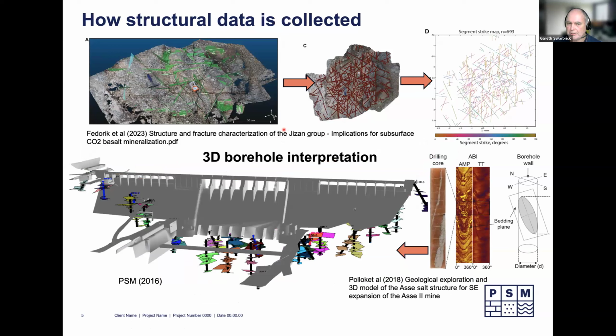How do we collect this data? There are a few different ways. Most commonly now we use something along the lines of the scanning electron microscope, but at a macro scale. We use photogrammetric techniques. We use LiDAR that allows us, in 3D, to pick up different defects within a particular mass of rock. We can then create 3D images and 3D constructs in real space, so this is in the actual scale of the features themselves.